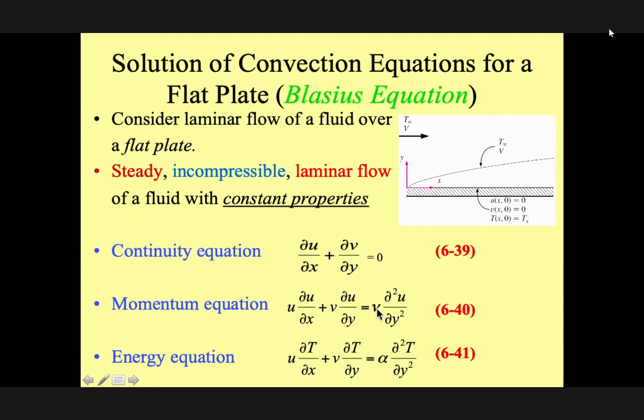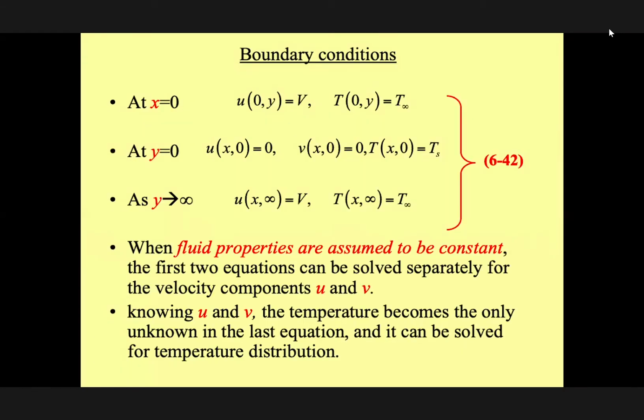Of course, it's a kinematic viscosity. It means viscosity divided by density. And I have here also thermal diffusivity, again rho, Cp, and k. Therefore, again, we have to make an assumption. We are trying to solve all of them assumed to be constant. They are not a function of x. They are not a function of the temperature, okay?